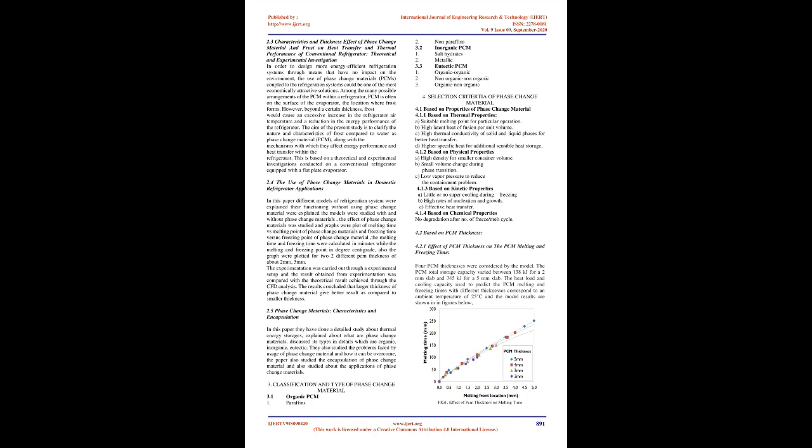However, beyond a certain thickness, frost would cause an excessive increase in the refrigerator air temperature and a reduction in the energy performance of the refrigerator. The aim of the present study is to clarify the nature and characteristics of frost compared to water as phase change material, PCM, along with the mechanisms with which they affect energy performance and heat transfer within the refrigerator. This is based on theoretical and experimental investigations conducted on a conventional refrigerator equipped with a flat plate evaporator.